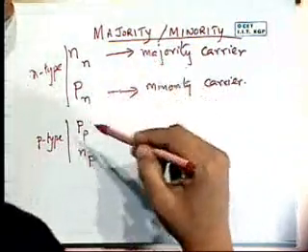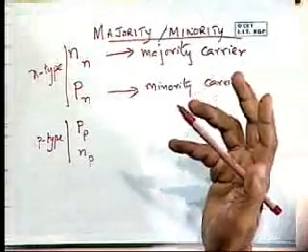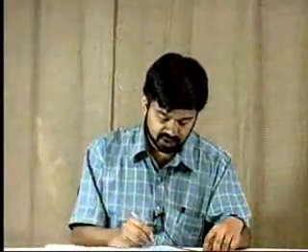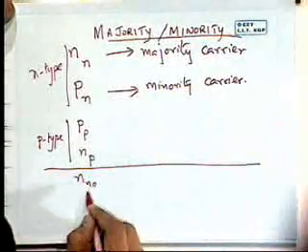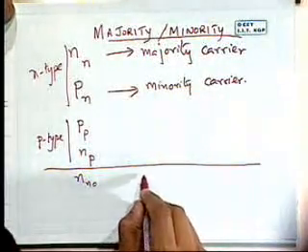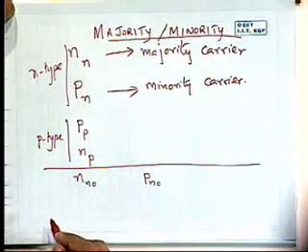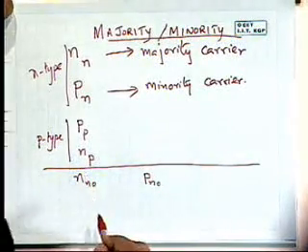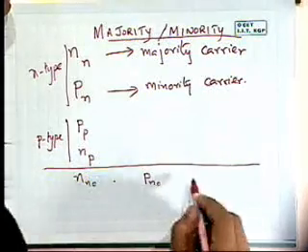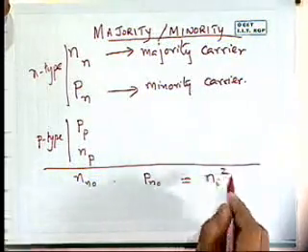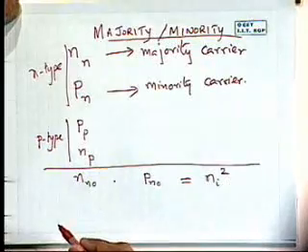And we noted that these are the instantaneous values at any given instant. Accordingly, we also introduced the equilibrium notation n subscript n naught, or p subscript n naught, as the equilibrium values. And sticking to an n-type semiconductor, we noted that this product is equal to Ni squared, which was known as the law of mass action.